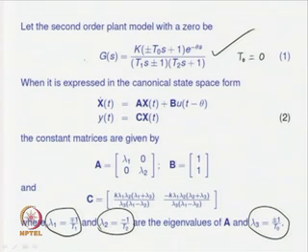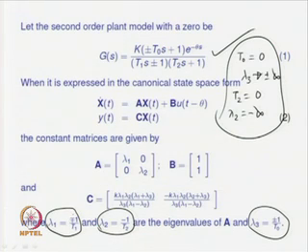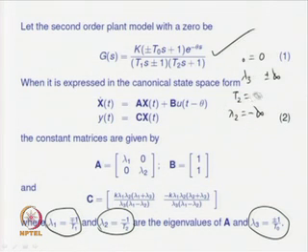In that case, we get a second order plant model without zero. What happens in that case? Lambda 3 will tend to plus minus infinity. Similarly, when T2 equal to 0, lambda 2 will be equal to minus infinity. To emphasize the point, when T0, T1, T2 assume different values, the lambdas can be approximated by large or small numbers accordingly. So, the lambda values can assume some limiting values depending on the type of transfer function model we are going to estimate.